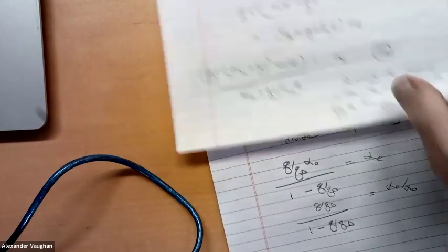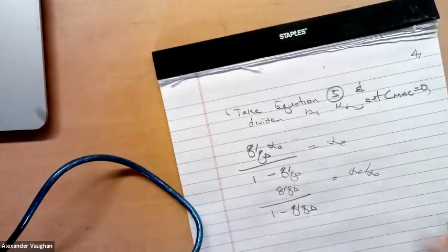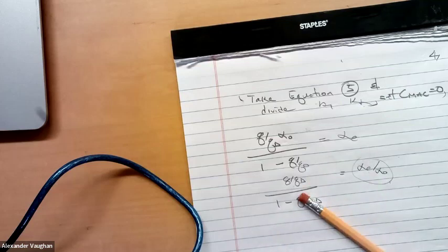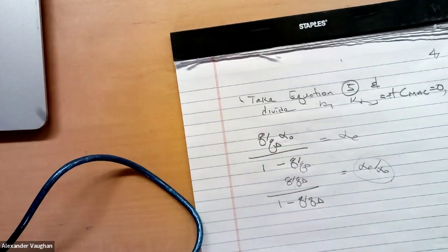This gives me really the essence of what's going on, because I'm normalizing the twist by the initial angle of attack and seeing how big it is relative to that. And I'm normalizing Q by the divergence Q. I'm seeing how big it is relative to that. If Q over Q divergence is small compared to 1, I just have that, right? So I'll call this equation 6.